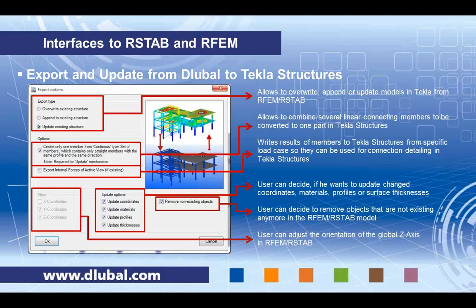On this main girder you have additional cross beams that connect somewhere along this main girder as secondary girders. And when I analyze it inside Dlubal software or typical all other software, then you have to make a connecting node where those intersection points are. So inside you have actually 3 analytical members maybe where there is only one major part in Tekla structure.